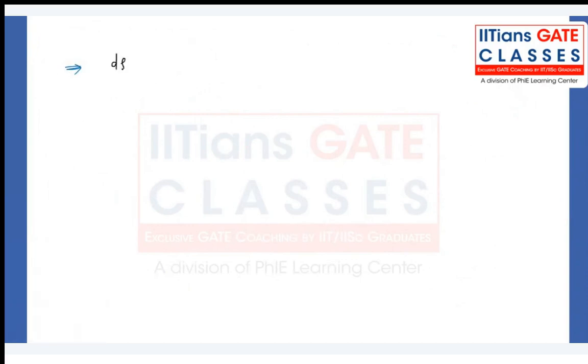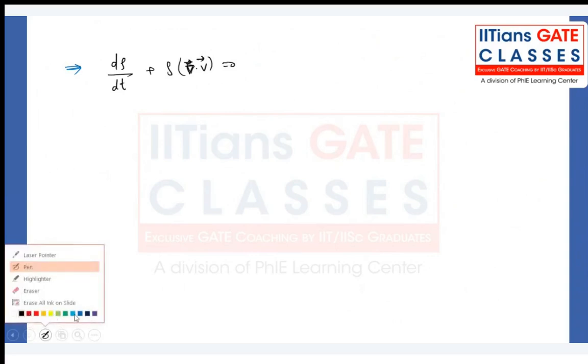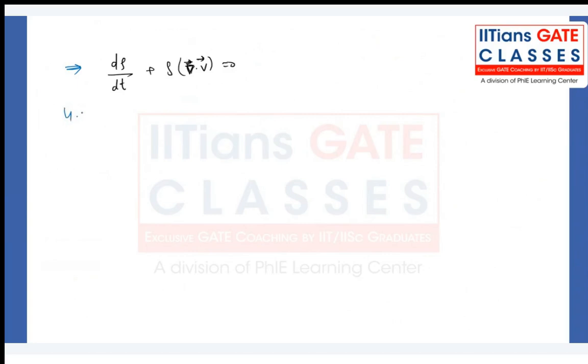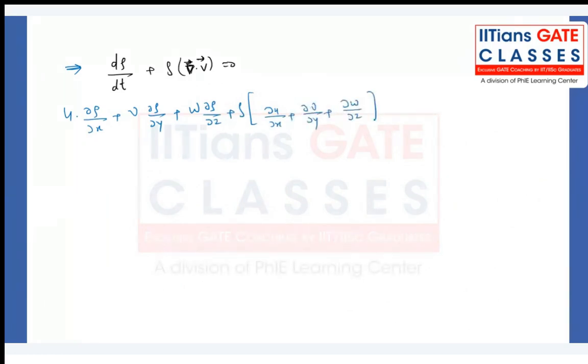D rho by dt plus rho del dot V has to be 0. Now, understand what we are understanding from here. If I just simplify this equation: u into dou rho by dou x plus v into dou rho by dou y plus omega into dou rho by dou z plus rho into dou u by dou x plus dou v by dou y plus dou omega by dou z plus dou rho by dou t. That is a full-fledged complete equation we have, right?